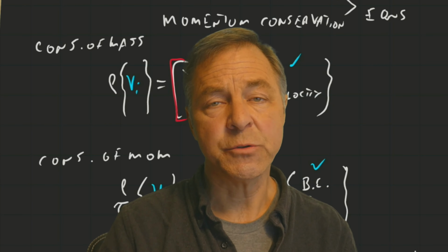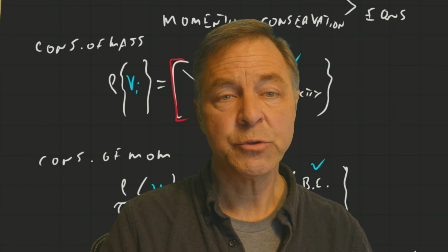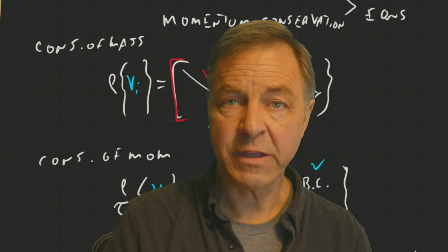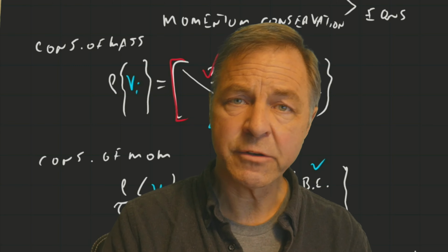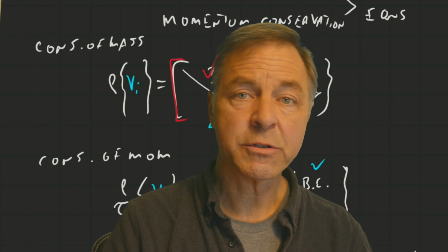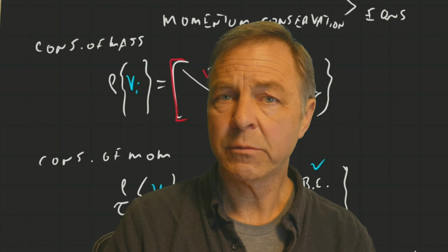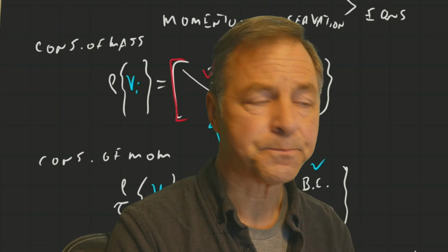And so we need to make sure we have a computational volume that's big enough to span the area where interesting things are happening. If we don't get those two factors right, even though you might get streamlines that look sort of okay, the result will be really not very reliable.